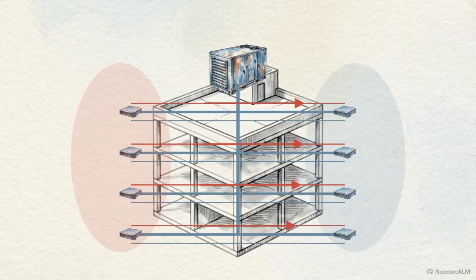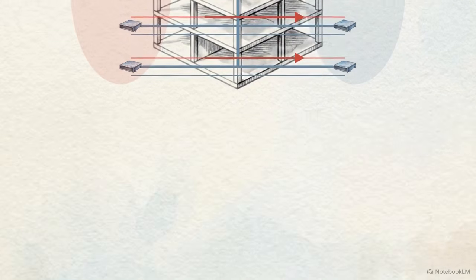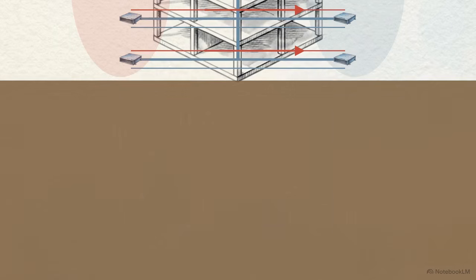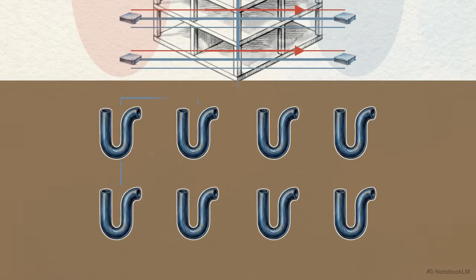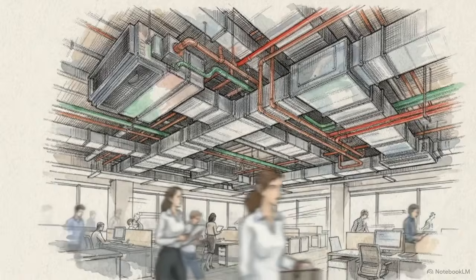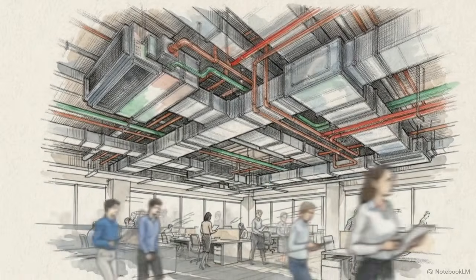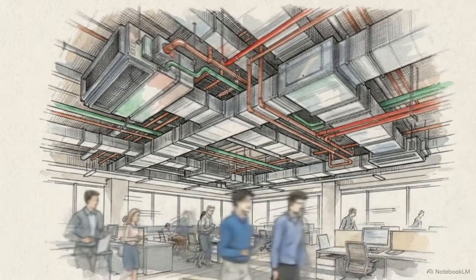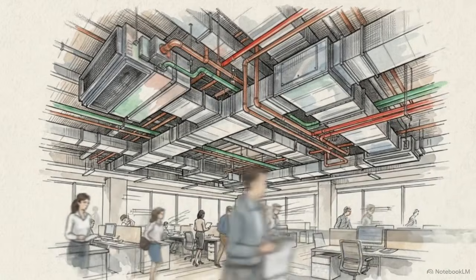Notice how it dynamically routes excess heat from the sunny south-facing facade directly to the shaded north-facing zones. Finally, the entire network is anchored deep into the earth by a ground-coupled well field, establishing a highly stable thermal sink. Removing a massive central air handling plant does not simplify a building's mechanical profile. It distributes that thermodynamic complexity directly out into the individual zones.